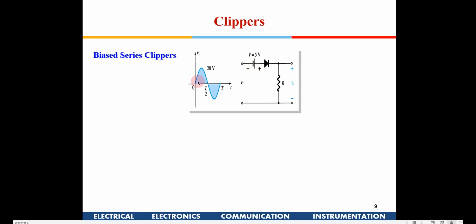If the input voltage is minus 1, still it will be forward biased. If it is minus 2, it will be forward biased. So the output will be available here. As long as in the negative cycle, only when the signal drops to minus 5, this diode will have 0 across it, and it will get switched off. Again we are neglecting that 0.7 in this case also.